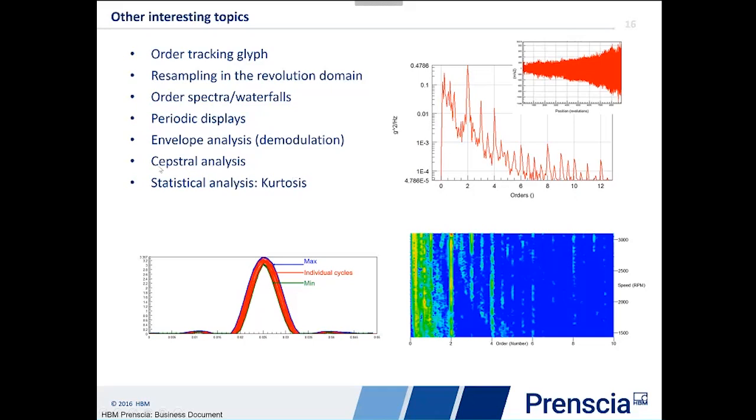detecting faults, we've got the kurtosis as a statistical metric. So you could do the global kurtosis on your signal, or a running kurtosis. So every 10 seconds, every minute, say, on a signal, you calculate the kurtosis and see how it evolves with time. So that's another metric that tells you whether something's going wrong, say, in your signal.